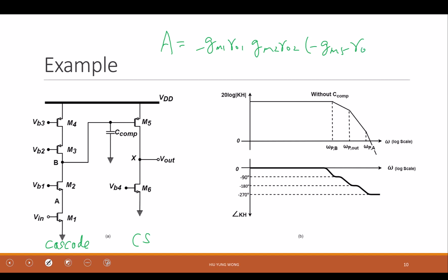I mean, of course, this is a little bit troublesome because we have two, M5, M6, with M6 as the bias. It would be better if we put it in this way, right? But that's okay. I mean, just in the order of gm ro cubed, a very high gain. We're talking about maybe 1,000. That's a lot. 1 millivolt becomes 1 volt, 1,000. And it's so easy to make, right?